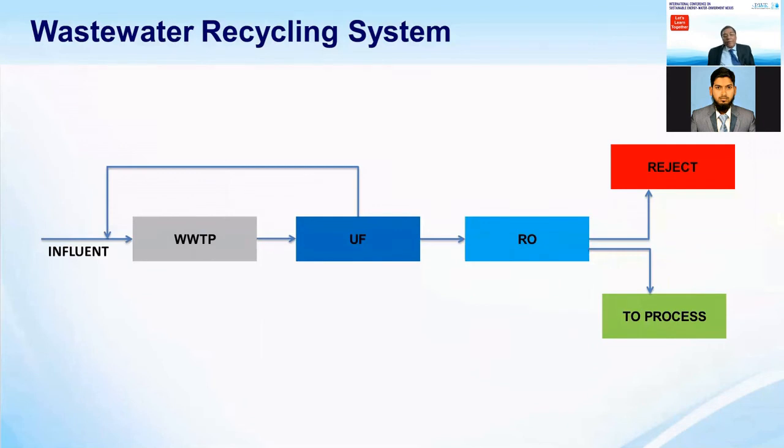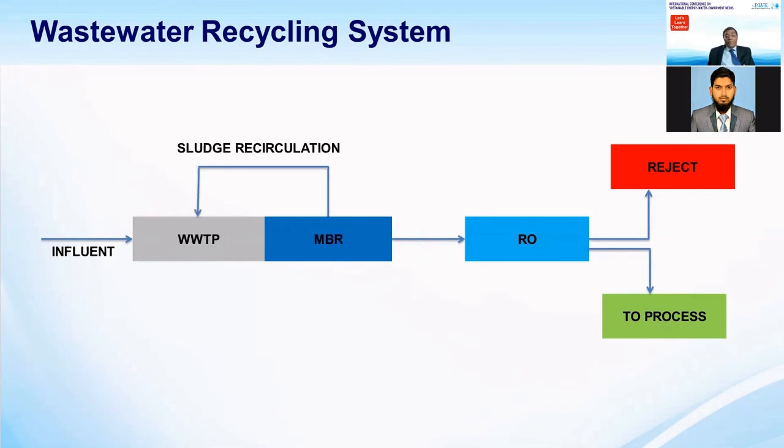Now I go back to the case where you have an existing system. You will have to install UF and RO after wastewater treatment for recycling of wastewater. And if you are setting up a new facility, then you don't need to put in a UF.